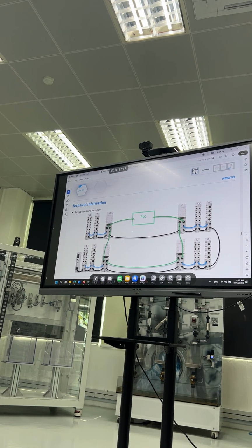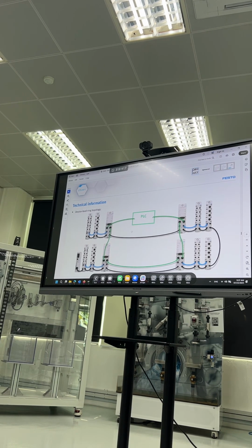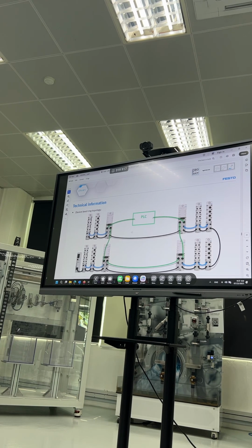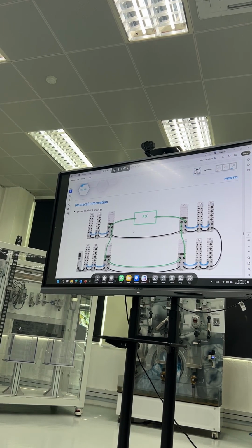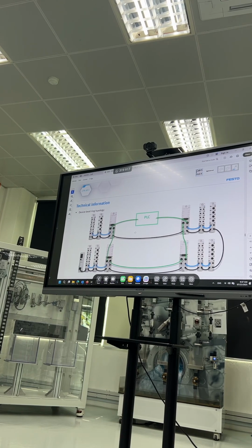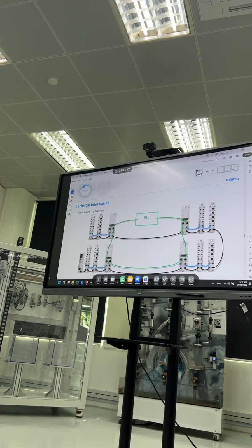One way you can test that is to connect from the PLC to the input of the devices, or connect from the PLC to the output of the devices. If both of them work, then you have redundancy on the device. So you mean we can test from our EtherCAT master, connect to the output port of the slave, and if it works, it should have it. We can see that with Ethernet IP, plugging into either input or output will work.